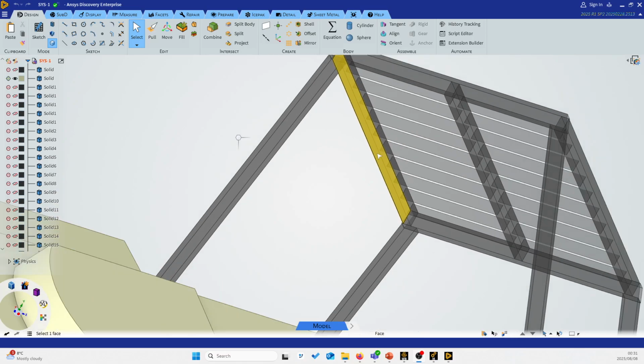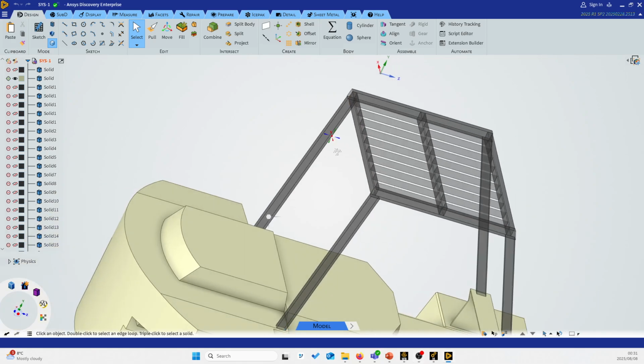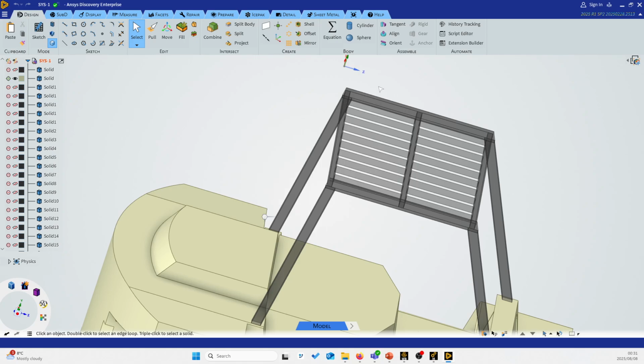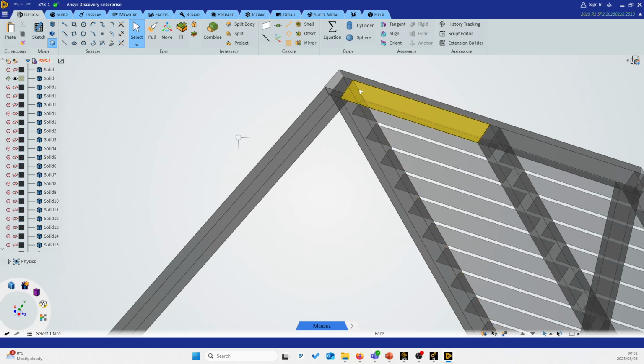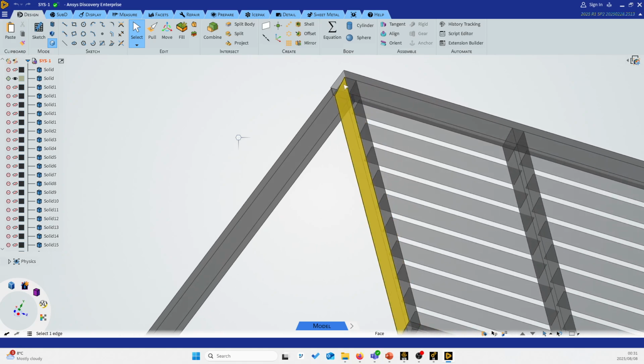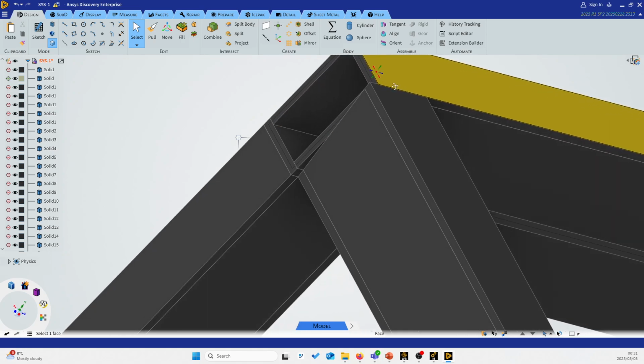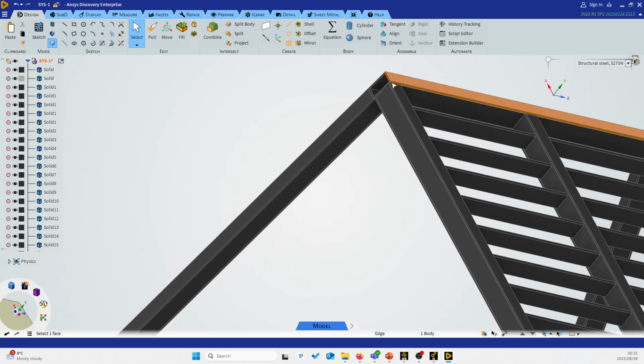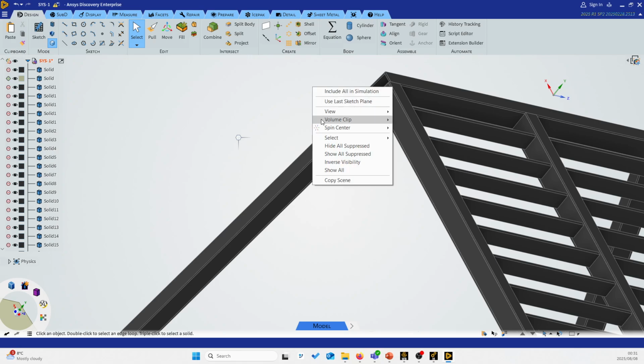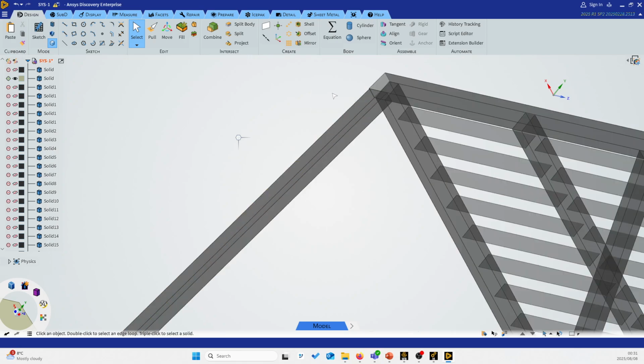Okay, so this is the geometry that we used for our cabin in the ROPS test. You can see here all these beams. I've gone ahead and mid-surfaced them. If you go here and show all, you can see that originally these were solid beams, and all that we did was cut them up and then mid-surface them. At the end we end up with something like this, where we have these mid-surfaces, and between these mid-surfaces we have the topology shared, so that they behave as if they're one solid structure that's bonded.